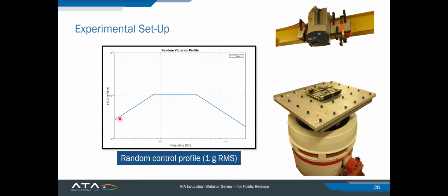We were testing it with this random vibration profile right here. This PSD is increasing until about 80 hertz, has a constant level until about 250 hertz, and then is decreasing logarithmically until about 2000 hertz.